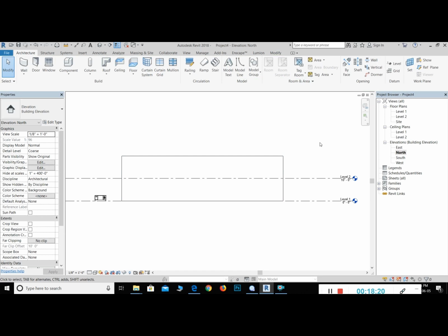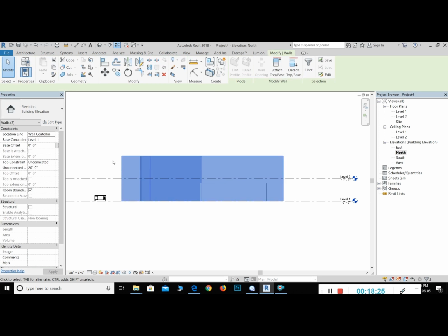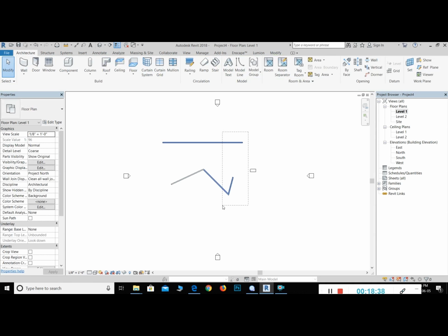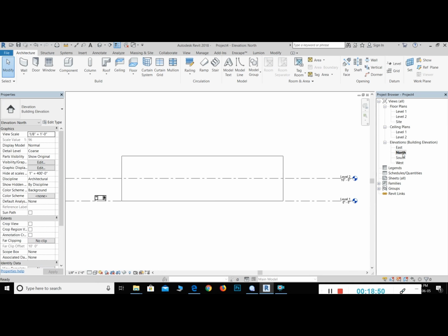What you can do, one option is to select all walls in here. As you can see, this one is at 8 feet, so these are going to be 20 feet. If you wanted, you can just click on here, but I don't suggest it because some of the objects like the desk or something are going to be selected again and it's not going to work. But you can go into the elevation, and then everything above 10, you can just select.